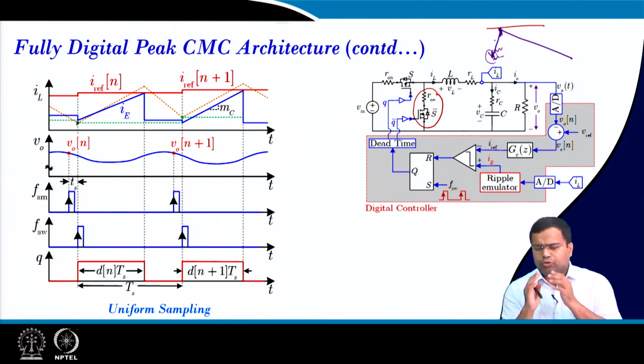That is why for low duty operation in analog control, people go for constant on time control, because if you go for valley current mode control, where you have a longer duration of off time, it is inherently unstable for low duty, and that we have discussed in our previous NPTEL course, that is control and tuning method in switch mode power converter.